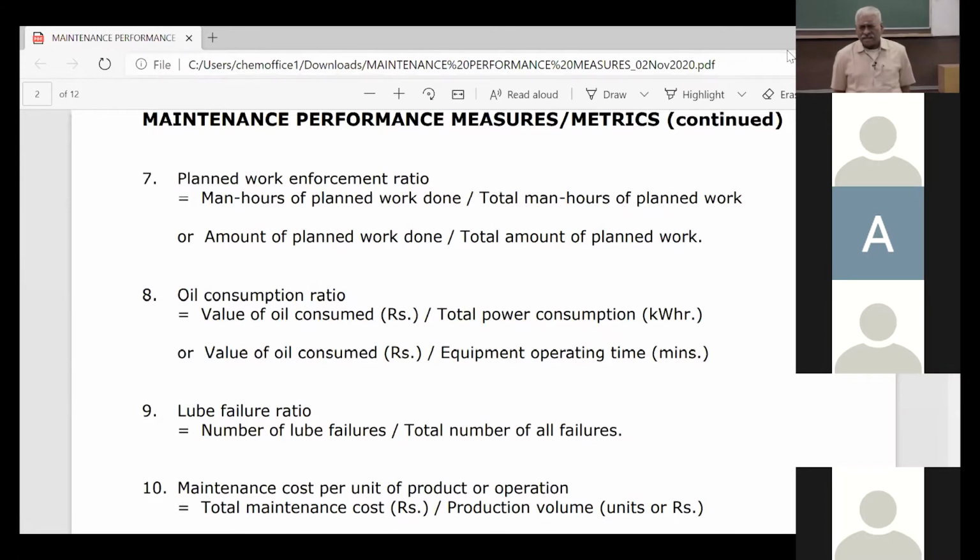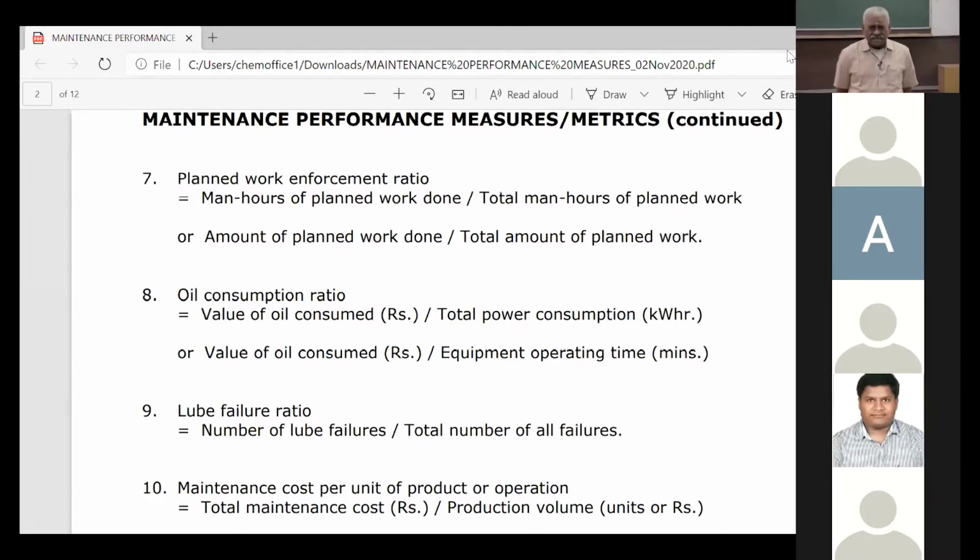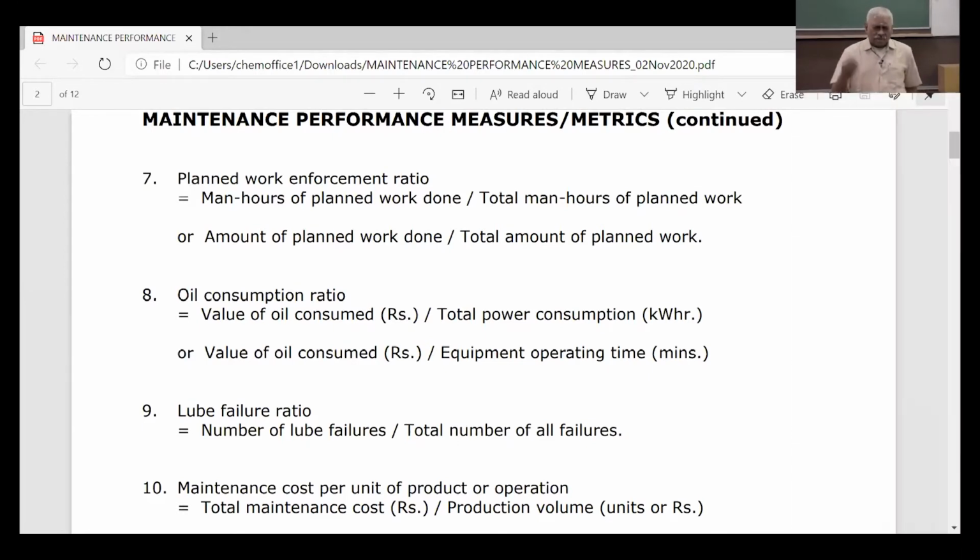Anything else? There may be friction in the parts. Yes, absolutely. That's more specific. Ariman's answer was correct that you need more maintenance. I was trying to get at a specific answer. It means that a greater amount of current is being drawn by the equipment, isn't it? So greater power is being drawn for the same voltage drop across the equipment, which means there's something wrong with the alignments, with the friction, wear and tear, etc.